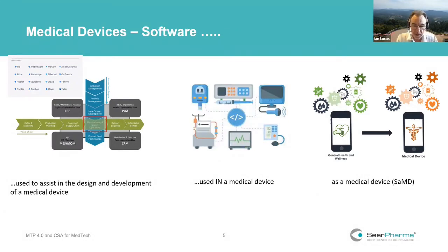What are the key aspects of that process that affect the outcome of the device, of the process, whatever it is? If you can define what they are, then you can define the critical process parameters around it, so the control parameters: temperatures need to be kept within a certain range, humidity needs to be kept, time needs to be kept within a range.